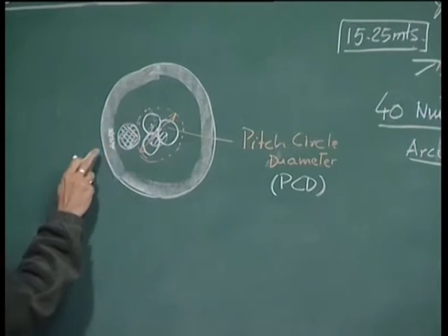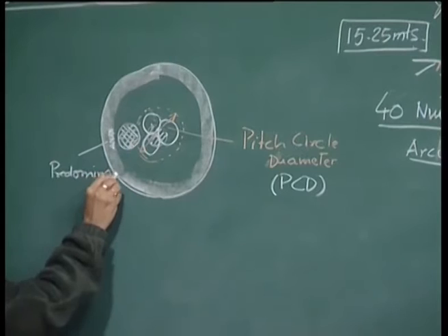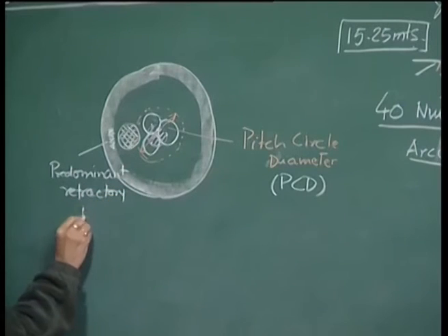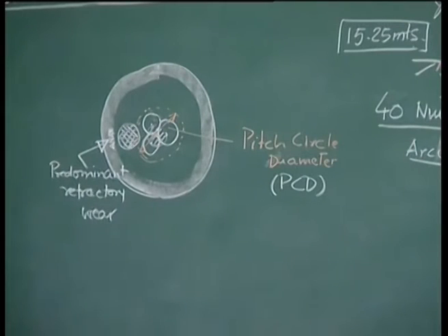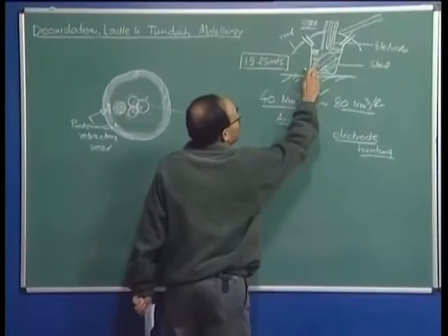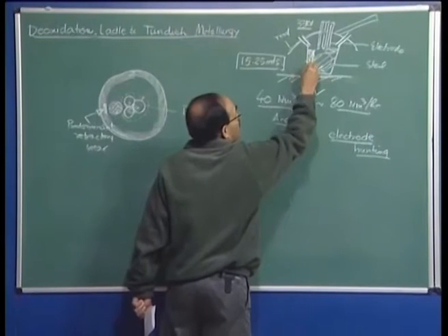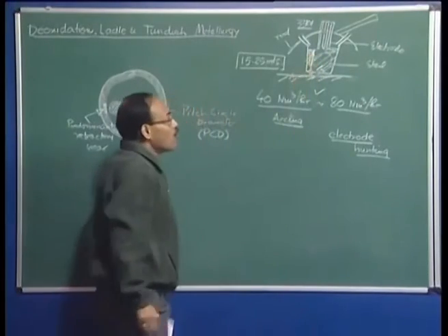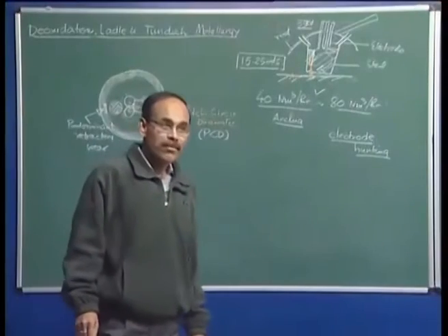So, therefore, you will see predominant refractory wear in the vicinity. So, this is the region where we are going to see a considerable amount of refractory wear. Why is it so? Because the bubbles are rising here, the high velocity regions are located here. So, it is a very high downward velocity which comes close to the wall, okay, and because of this high downward velocity, which is shown by a red arrow here, the hydrodynamic erosion of the refractory bricks is very